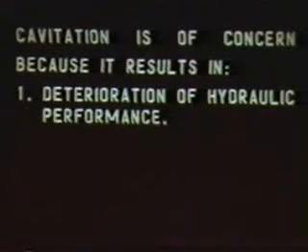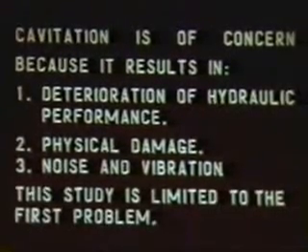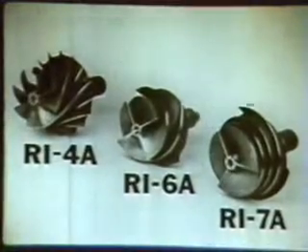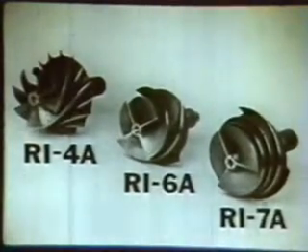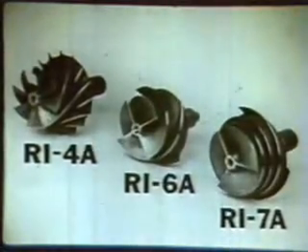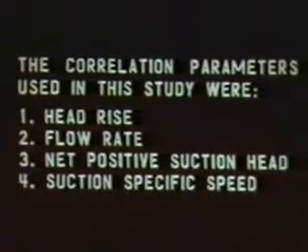Cavitation is of concern because it results in deterioration of hydraulic performance, physical damage, noise, and vibration. This study is limited to the first problem. This film presents a correlation between visual cavitation data and hydraulic performance parameters for these three mixed-flow impellers. The correlation parameters used in this study were head rise, flow rate, net positive suction head, and suction specific speed.